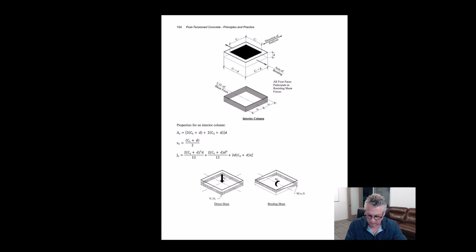Remember, in a beam, we look 2-dimensionally at the moment of inertia. And we had a moment of inertia of BH cubed over 12, and a section modulus of BH squared over 6, and we were calculating the stress at the extreme faces due to bending. What we're doing here is the same thing, but 3-dimensionally.